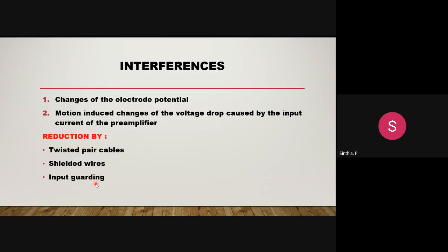Recording of the biopotential is often done in an environment that is equipped with many electrical systems. So there is probability of producing strong electrical and magnetic fields. In addition to the 60 Hertz power line frequency interference signals, some other strong harmonics or some high frequency electromagnetic fields can also be generated as interference signals. The electric and magnetic components of the interfering fields can be considered separately.